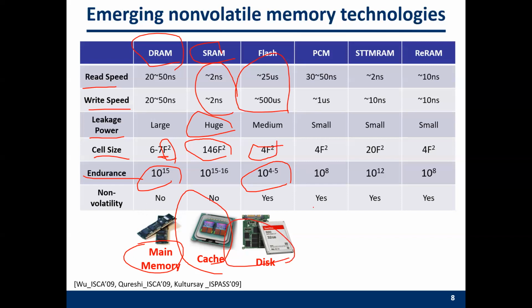So in this lecture, I would like to introduce some other memory technology, like the phase change memory. It's a new type of memory technology. It has very small cell size, longer endurance than flash, better reliability than flash. The read latency can be comparable to the DRAM, but the write latency is much longer than DRAM, but it's still much faster than the flash.